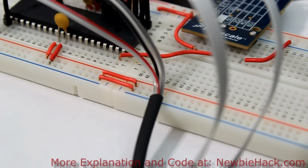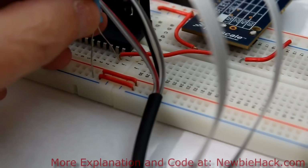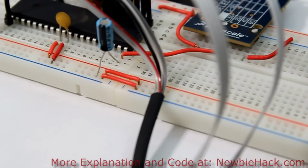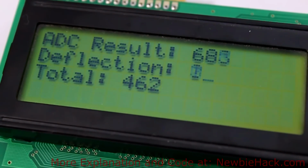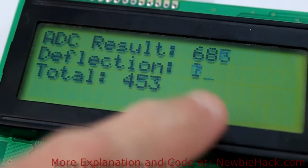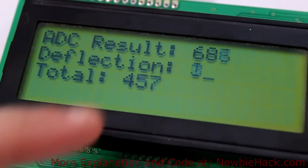I'm going to turn it off. I'm going to put in the capacitor, positive side to pin AD0 and negative side to the ground rail. So let's see what happens with the samples and the deflection. Okay, the total now is down to 460, and you can also see that there's only 1 digit here, and I can see maybe a maximum of 3. I don't think there's a 4 in there, but 450,